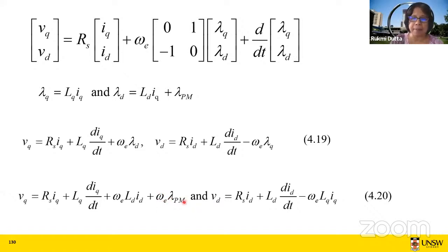If you remember the DC motor, it is the flux times speed, and a constant, which gives you the EMF. So now it becomes very similar to a DC motor. In a DC motor, you have a resistance and an inductance, because the winding has an inductance, right? So we usually have RA and LA, and then you have the EMF. RA is the armature resistance, LA the armature winding inductance, and then the EMF.